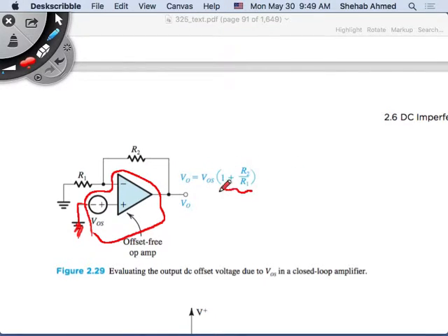You will measure that gain multiplied by some offset voltage. So if you know that the input you have placed is 0, and you know your resistors, meaning you know your gain, you can calculate your offset voltage. You did not put anything external. So the only thing that's causing gain now is your resistors and the offset voltage. So you know what your offset voltage is from that perspective.